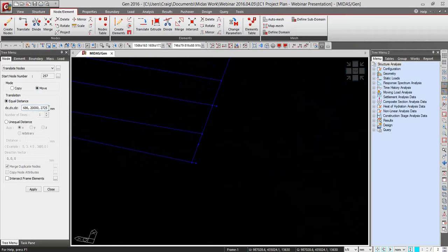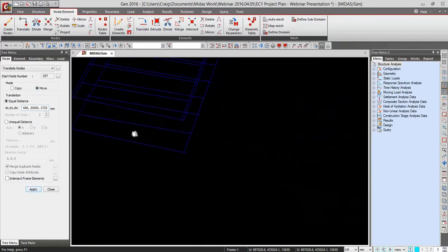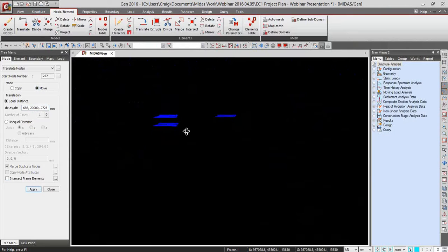And then I've allowed for the height of each floor to be edited, and I click apply. So here the 6th floor is in place directly above the 5th floor, and I'll do the same again and move the roof plan.